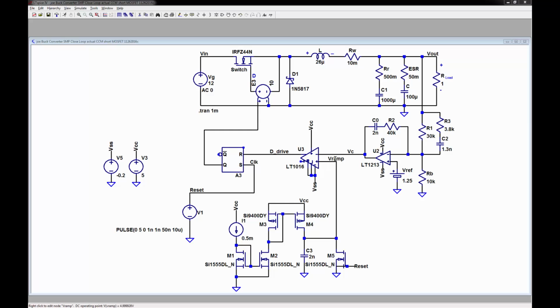And so when we create the ramp, this will create a circuit where I start my duty cycle here. Now, why do I need a voltage controlled voltage source here? Because I don't want to use a charge pump. A charge pump takes too much time for right now. We'll know later on, if you want to add a charge pump, we can add a charge pump and drive it. The reason why you need some kind of pump is I can't reference this to ground. This is not ground. This flies up to VN and flies down to minus a diode drop. So I have to have some way to gain this up, either through an isolated transformer to put a pulse in here, or a charge pump, and this will be my new ground for the charge pump, turning this on and off.